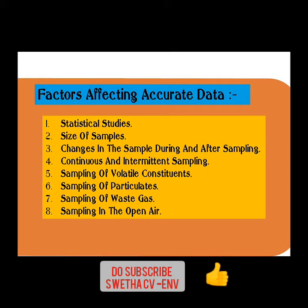There are 8 points. The major factors which are responsible for analyzing the sample to get an accurate result or accurate data. So what are these 8 points? One is the statistical studies. Second is size of the samples. Third, changes in the sample during and after sampling. Fourth is continuous and intermittent sampling. Fifth, sampling of volatile constituents. Sixth, sampling of particulates. Seventh is sampling of waste gas. And the last is sampling in open air.